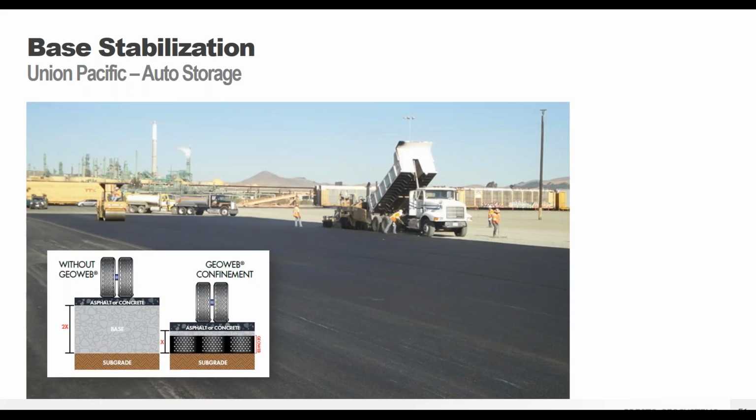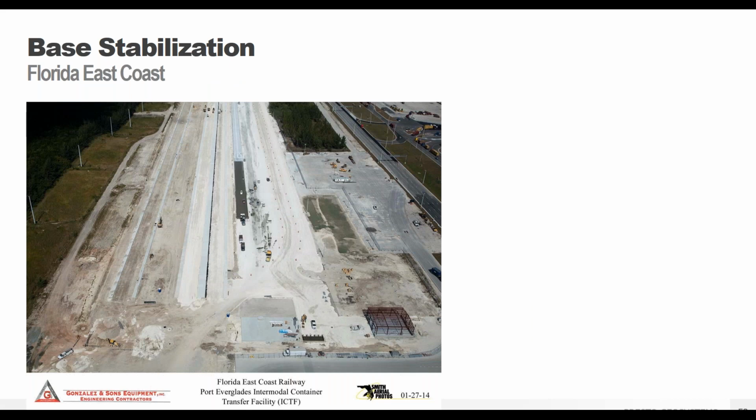And then you can see they were able to place about a 4-inch asphalt paving layer over top of the GeoWeb panels. And again, just regular asphalt is used, and it was compacted with a standard smooth barrel roller. No special equipment, no special procedures are required, so you don't need extra training for your asphalt crews or anything like that. So this was another project.